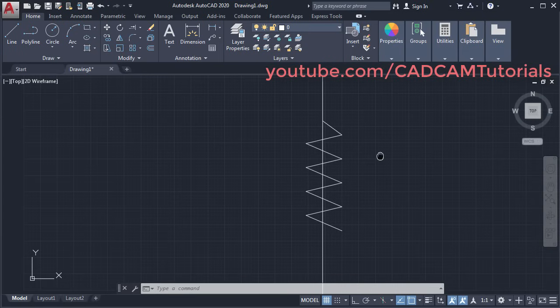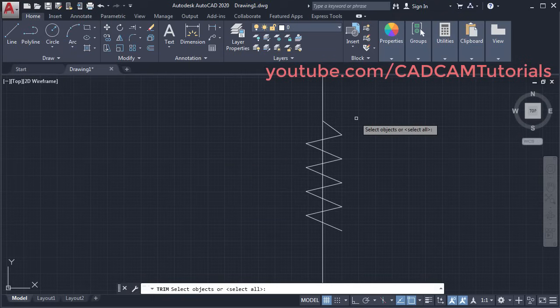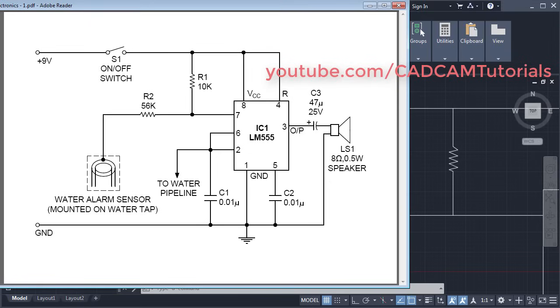Then zoom it, then trim the unwanted objects. For trim you can type TR, enter. Then specify boundary edges for trim. So I want to trim up to this line and up to this line, and I want to trim this line with reference to this line. Press enter, click on the objects to be removed and press enter, zoom minus. So this is also ready.